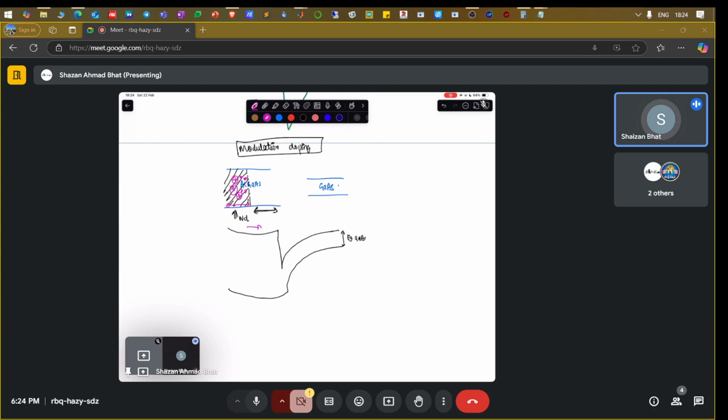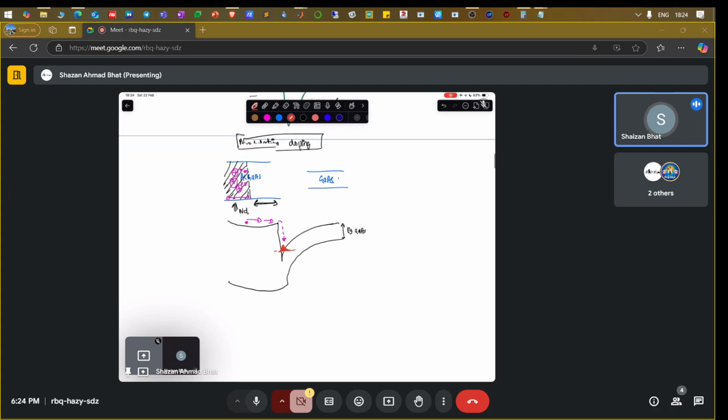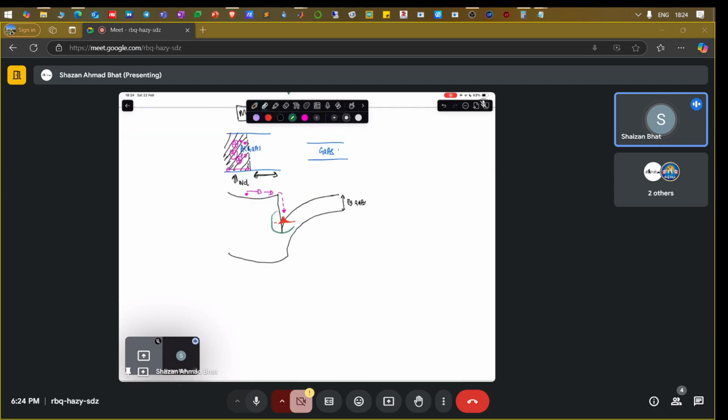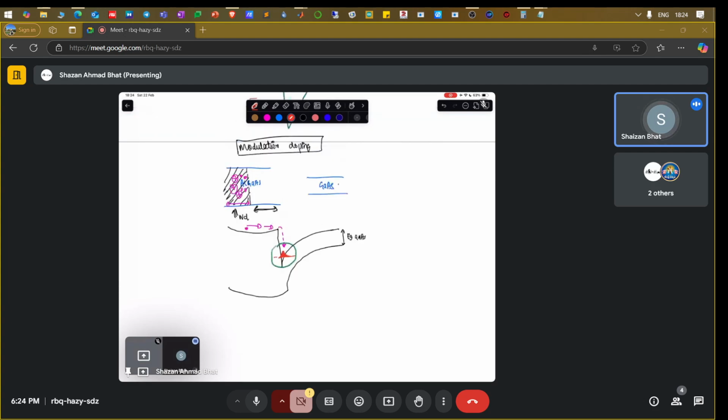Those electrons go down the hill and come down here, and because you have confinement here, you have the first energy value and an electron density which looks something like this. Now let's zoom into this region, because the electrons have come from the impurities of the aluminum gallium arsenide.